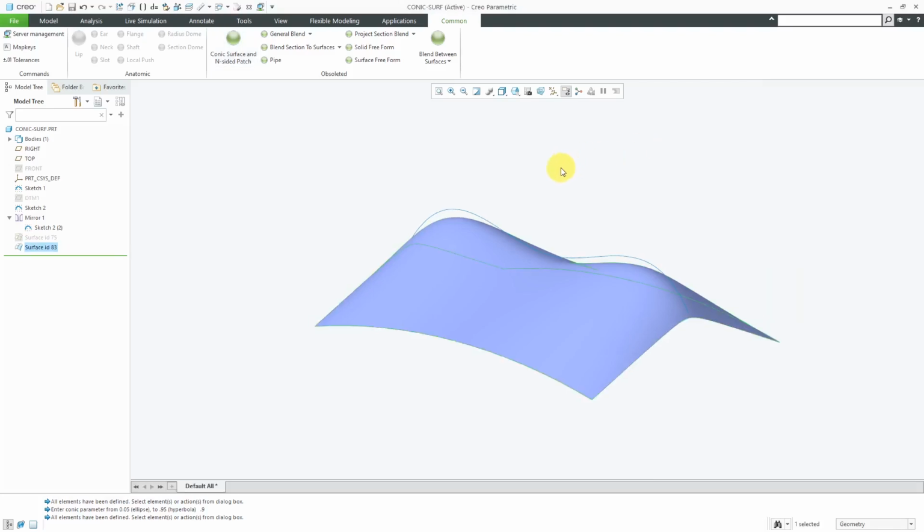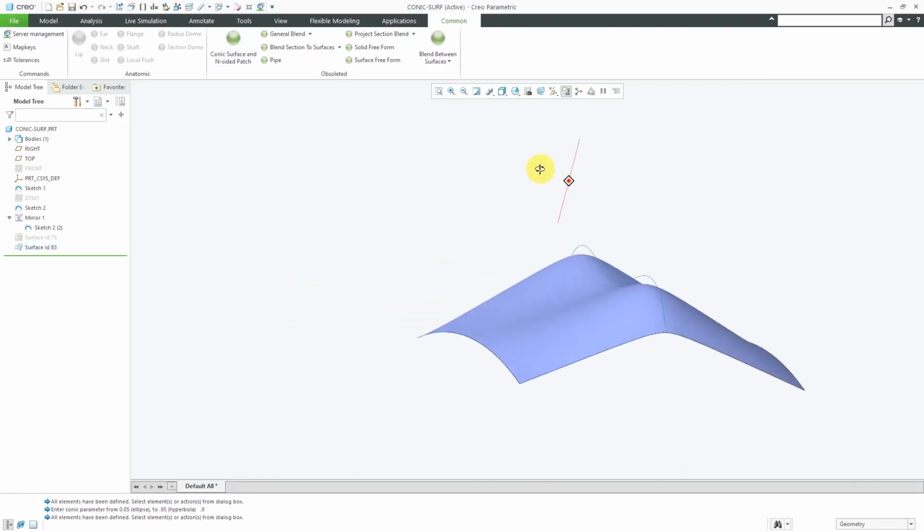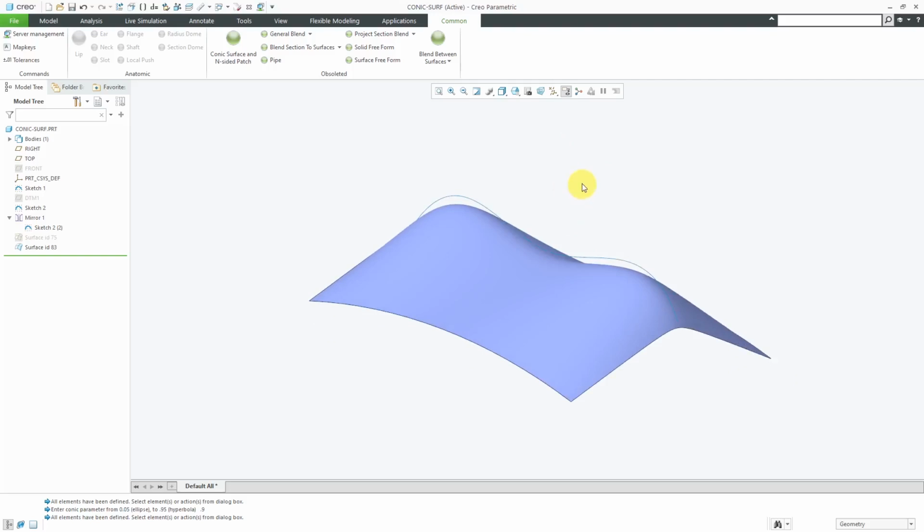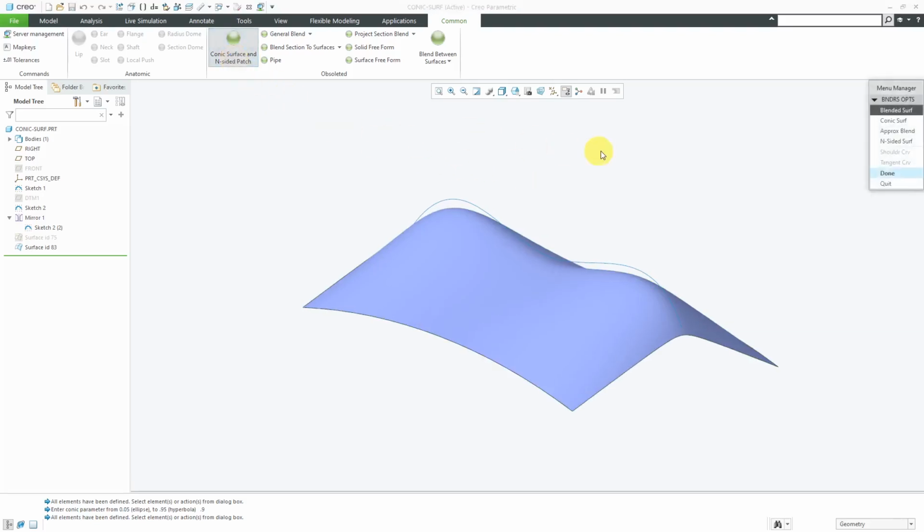Let me click the OK button out of there for this surface that is created in between there. But again, once you had the round feature that was capable of creating conic shapes with a rho parameter, this was really not that necessary anymore. But again, hey, if you need the option of having this as a shoulder curve with that conical shape, this is one of those commands that you might want to keep in your back pocket.